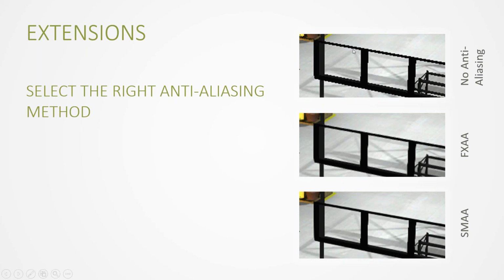So you can see that depending on your scene, you could have some jagged edges on your lines. So you could consider using either FXAA or SMAA methods. Now, FXAA will be more efficient in terms of processing power than SMAA, but it will have a slightly fuzzier look. Again, adapt this to the hardware you have available and the resources you have to dedicate to anti-aliasing. This can have a very material impact on performance.